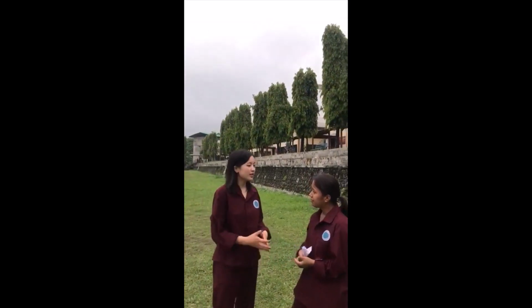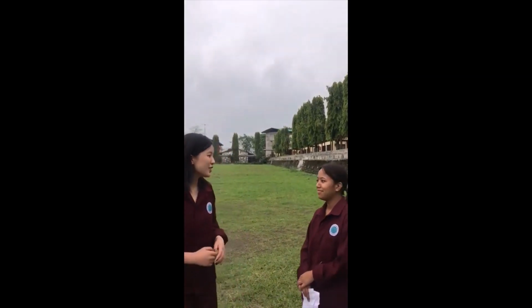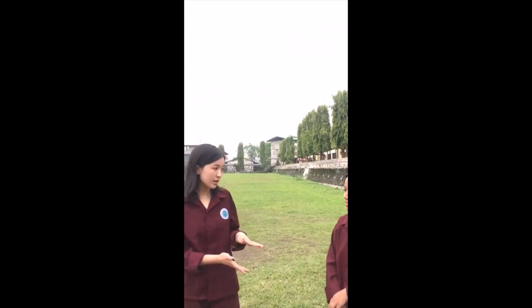Now, can you tell what the significance of this ERT test is? After learning about the ERT test, its principle, working, setups, and the ERT profile produced, I came to understand that it is of much importance. I think it could be used in bedrock mapping. It is also used to find the minerals contained in the soil and to know the depth of the water level. Wow, that's so impressive of you. So after knowing the properties of the subsurface, we can know if a particular construction is feasible over that particular land. So that's the significance of ERT.